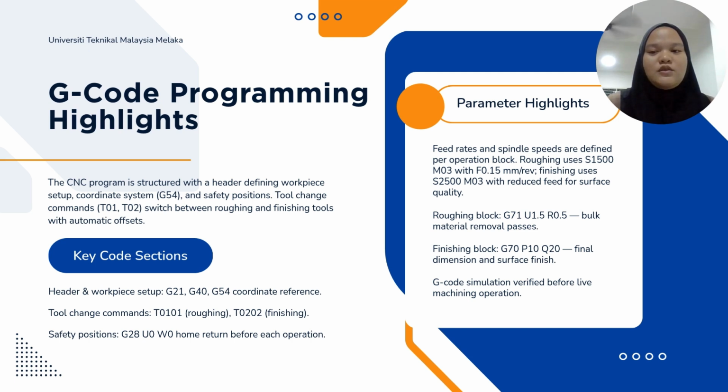Next, T0101 is used for the roughing tool, while T0202 is used for the finishing tool. Before each operation, G28 U0 W0 returns the machine to a safe position.